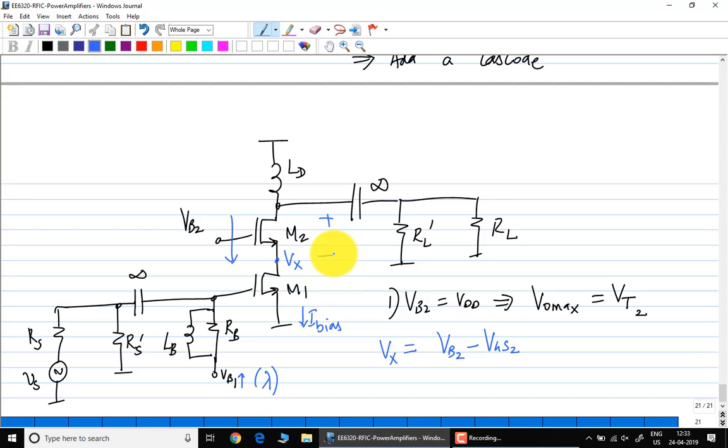These will all be significant in the PA because the transistors are going to be extremely wide, and minimum length. When I say extremely wide, if you want to put out max power, don't be surprised if you have transistors in the millimeters. 1 millimeter, 1.5 millimeters for the NMOS transistor is definitely possible. You want to put out 40 milliwatts of power, this is what you have to put out. I know you're used to 10 microns, 20 microns, but this kind of stuff will happen.